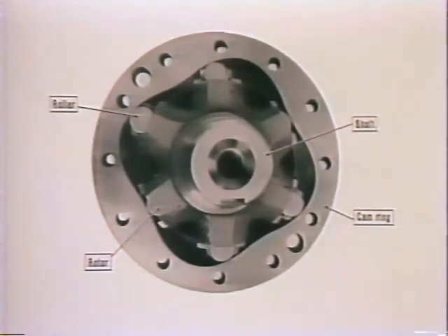Pressurizing the pistons in opposing pairs balances the hydraulic forces and eliminates hydraulic loads on the bearings. Their lightweight, compact design and high efficiency make them ideally suited for mobile vehicle drives, mining machines, and many similar applications.